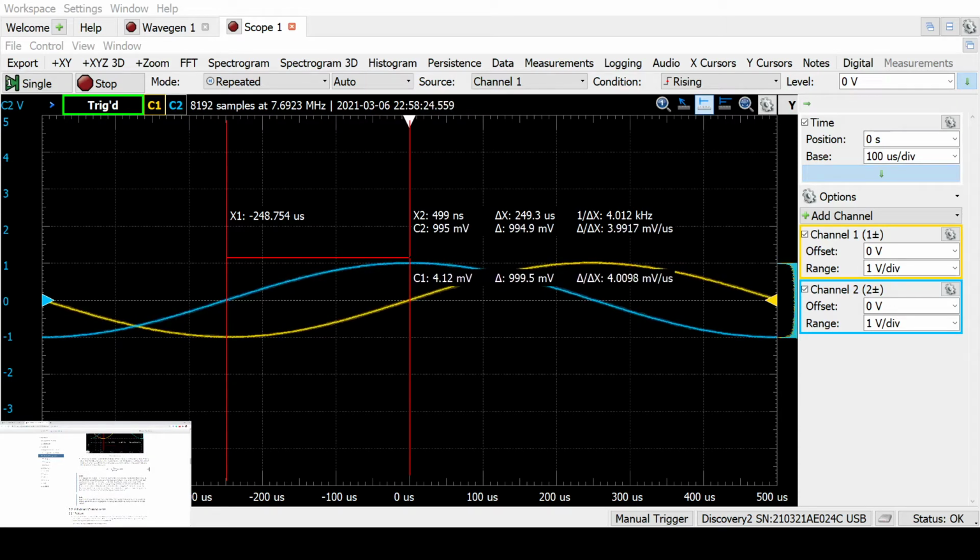Alright, when measuring the phase in time between two waveforms, it's important to measure the time starting with the reference waveform to the waveform under test to obtain the correct sign. So as we initially identified, blue is leading and yellow is lagging. So if we wanted to see the phase difference between blue and yellow and the delay of yellow waveform, then our reference will be blue. So we will start from blue and then measure the yellow one. So blue one is reference.